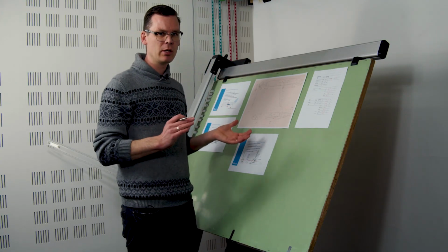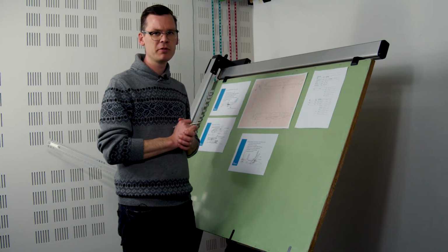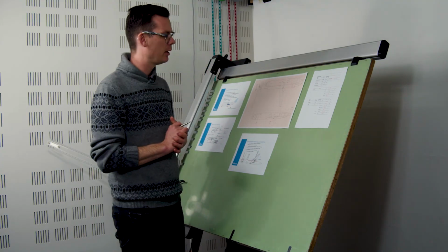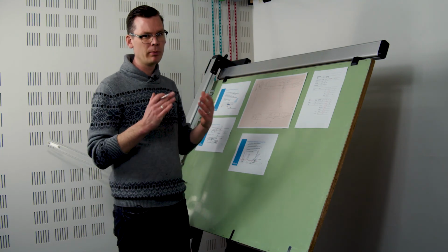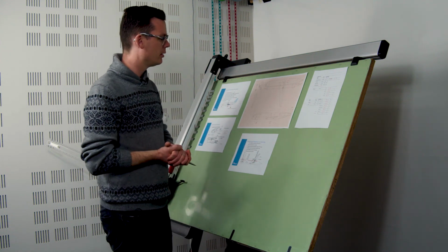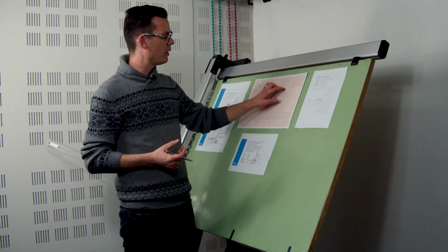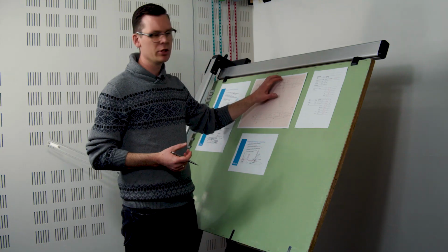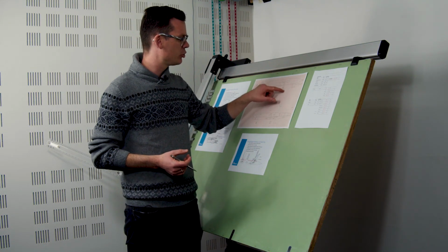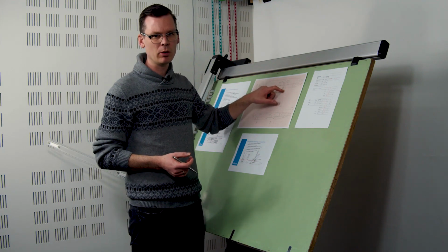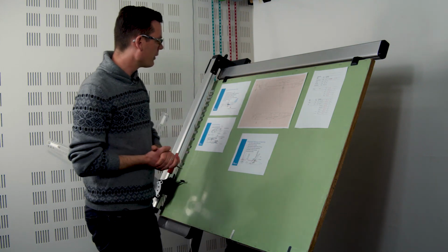So that means that you are going to be a little bit more conservative than what you have estimated in your wing loading diagram, and that's something to keep in mind, or maybe take into account in the next iteration, because now you can actually compute how much additional wing area you've added by adding this triangle, which we typically call a Yehudi. All right, so that finalizes the integration of the landing gear.